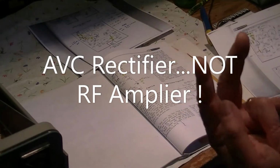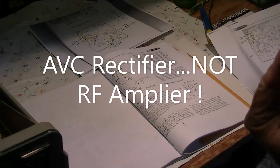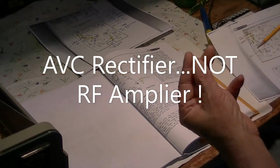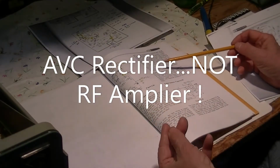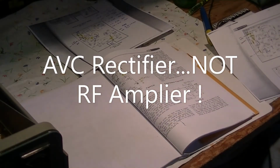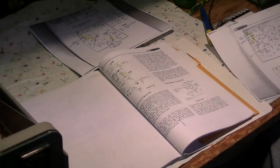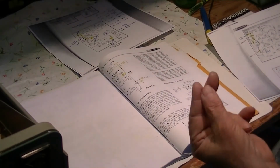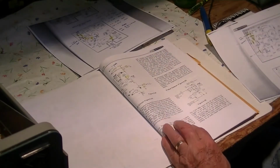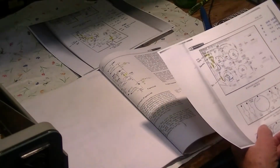There's a fast attack AVC resistor-capacitor combination, and the time constant of that capacitor and resistor makes for the fast attack AVC. And there's another pair that's the slow release. Fast attack, slow release is the kind of AVC that this has. There's another resistor-capacitor pair that are responsible for that. And there's a little voltage divider, and some bypass capacitors and a couple of other little resistors in here.